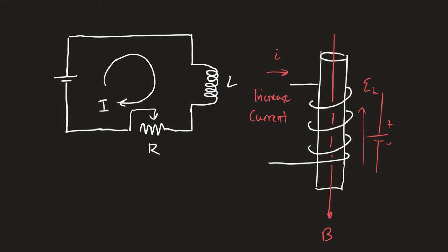We place inductors inside those power strips that say line conditioning, purely to make sure that the current flows at a uniform rate. Any spike that comes through is met with a natural back EMF to prevent it from going through. And if there's a dropout or a brownout, there's a natural boost. The energy in that field is used to try and maintain the current.